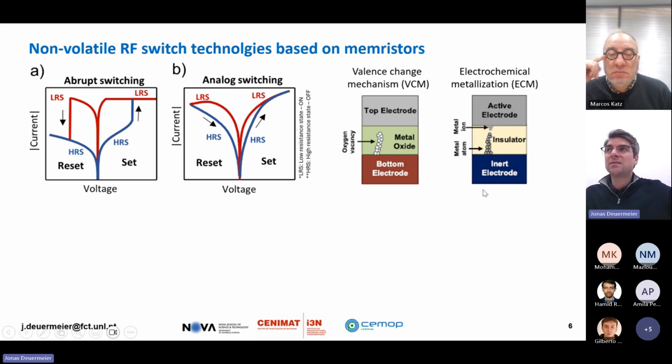So when we think of capacitance and resistance, the capacitance can be drastically reduced by nano-sized patterning of the electrode. But since the on resistance is purely dependent on the filament size, you are basically not losing on resistance by making the device really small. So even if the active electrode is really narrow, the on resistance is always going to be the same, because it is determined by the filament size itself, which is not dependent on the electrode area. So you can improve capacitance by making a small device without deteriorating your on resistance.